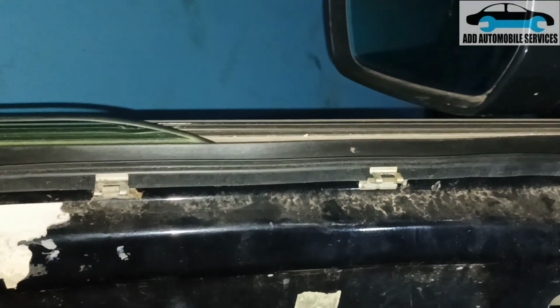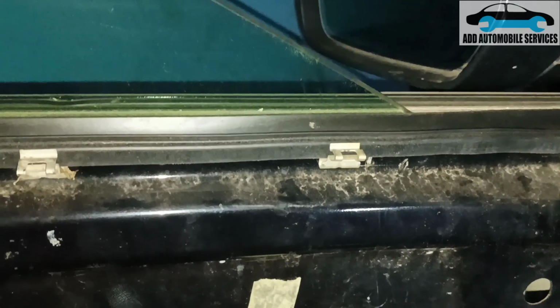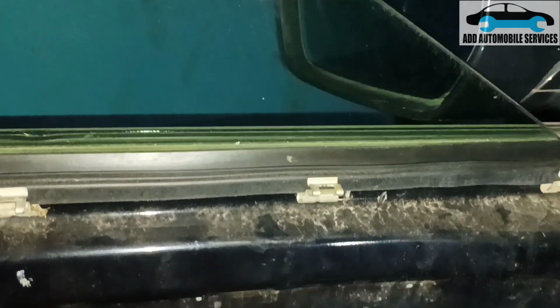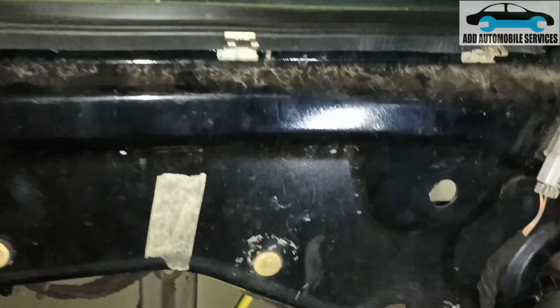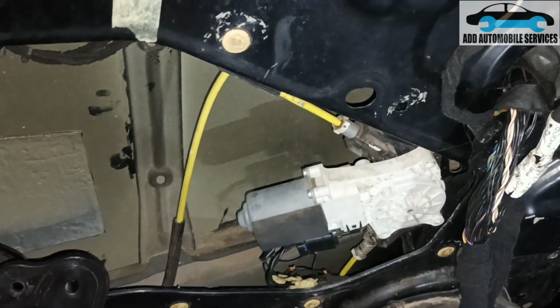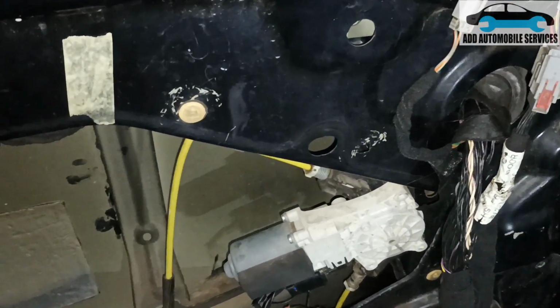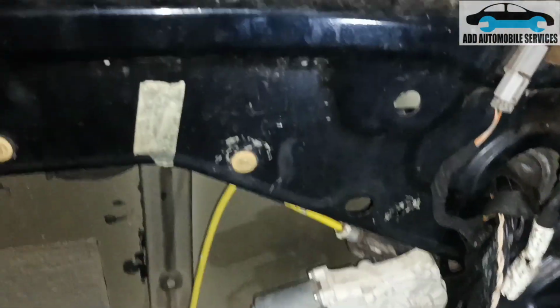Wow. And when you go up, because it has not been normalized, but when I hold it, it goes up automatically without pausing. So it was the Hall effect sensor wiring which was having the fault. So after doing it, now try and normalize the window and see if everything will work. But before that, I have to repair the wires and I'll call it a fix.